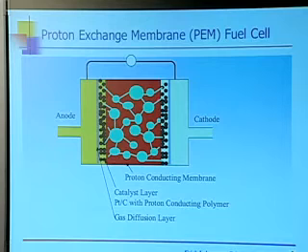That material, I don't know if you've seen it, but if you've seen a transparency that you use on an overhead projector, it looks about the same. There's not much different, just visually looking at it. The thickness here has been going down. About 10 years ago now, the standard thickness used, measured in thousandths of an inch, in mils, was 5 mils thick, about 125 microns across. And today, people build cells that are typically about 40 microns or 2 mils across, and they're trying to get down to 1 mil dimensions.